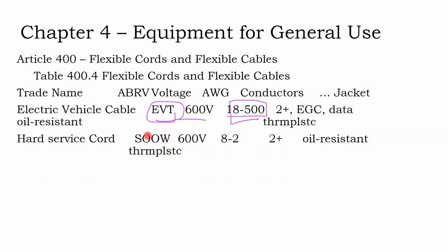I'm used to using kind of welder's cable inside of large battery banks for ease of wiring. Might have to look at the EV cable instead. There's a solar cable too. It's called PV cable. It's high voltage, with a super thick jacket, rated for exposure to sunlight, high temperature, and wet environments.